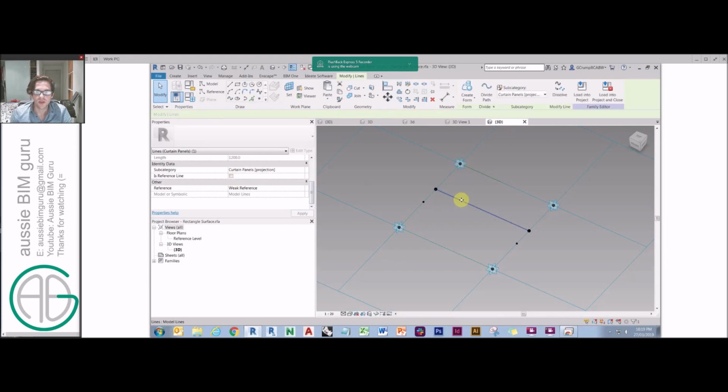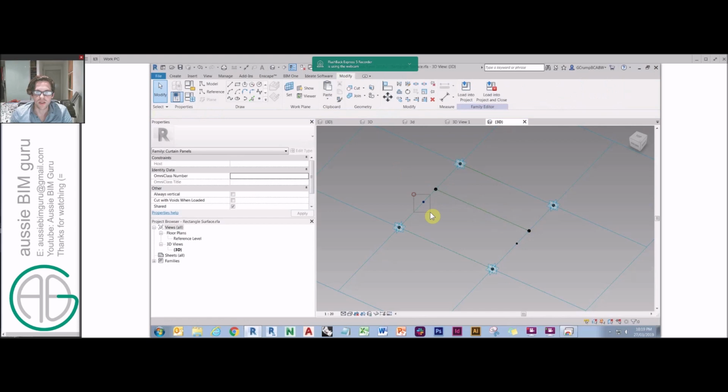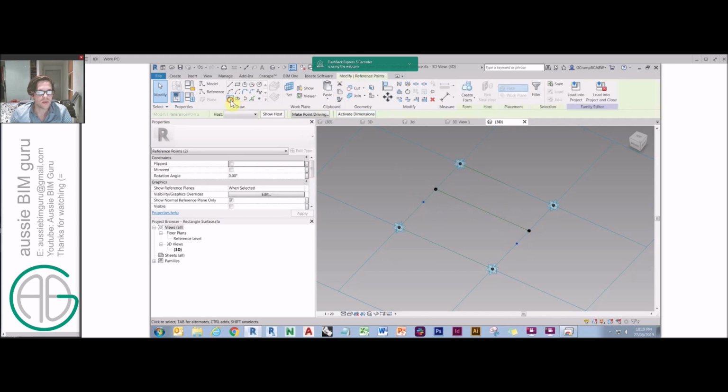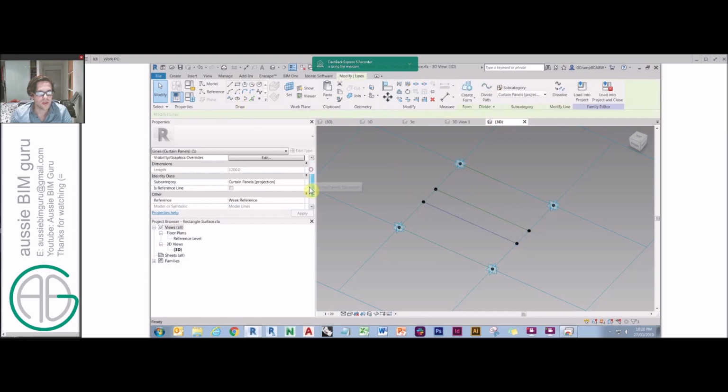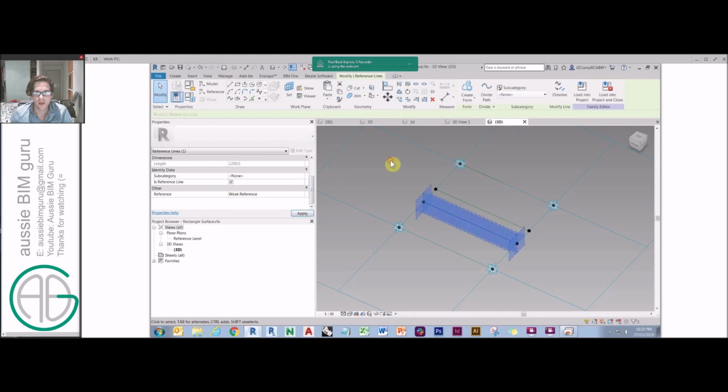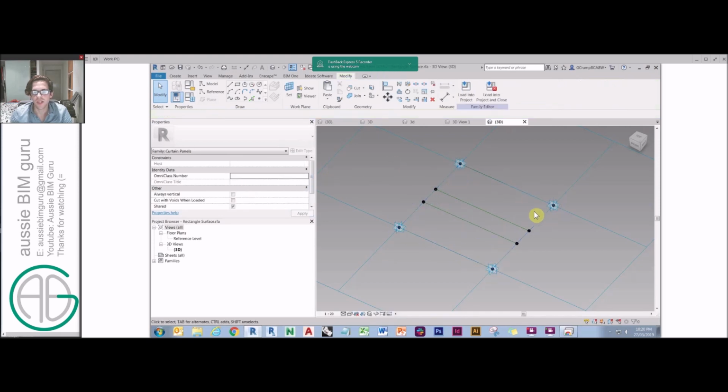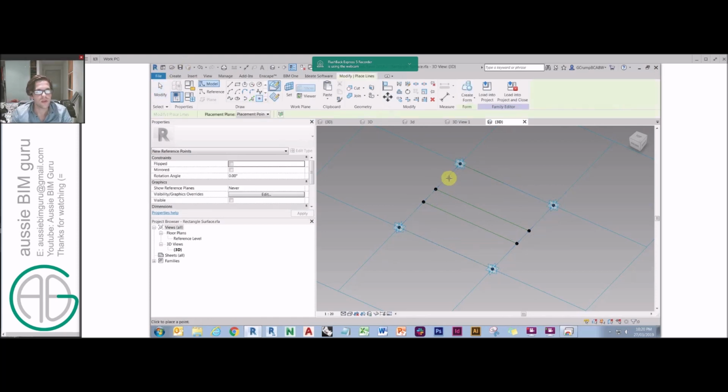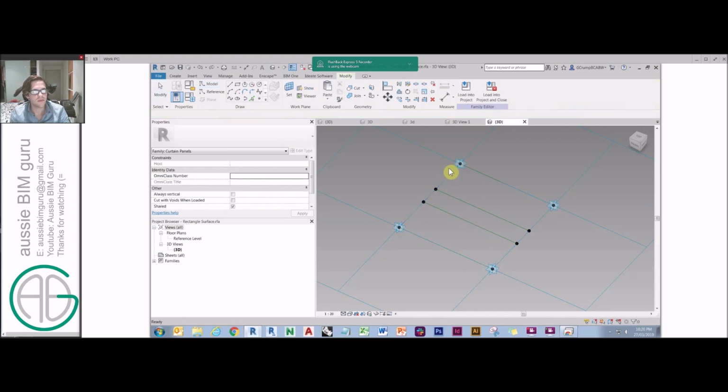You can source geometry using lines, but they get used up and become a part of the mass's definition once you use them to generate forms. So we want to use that multiple times potentially. Likewise, we'll generate another line as well. And there are 2 reference lines. We then want to make the bisecting line where the apex and the fold occurs on the panel. So we will create 2 points here.